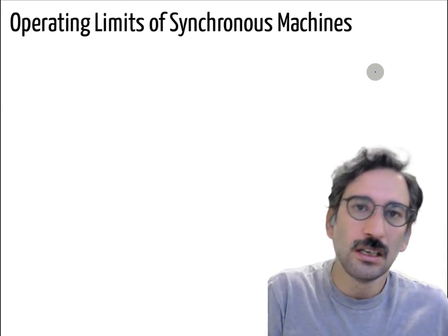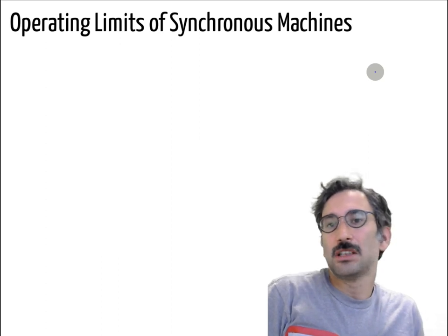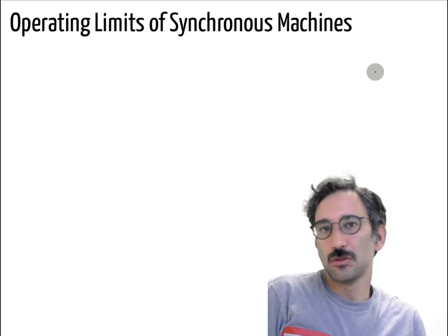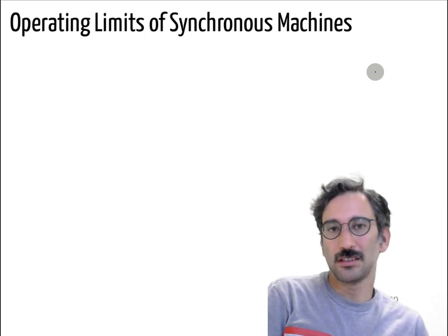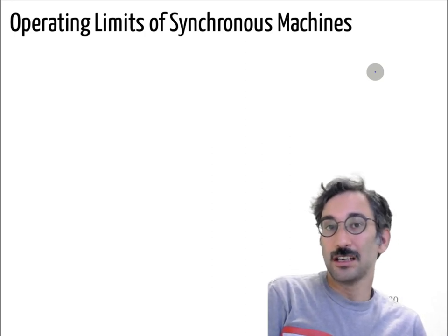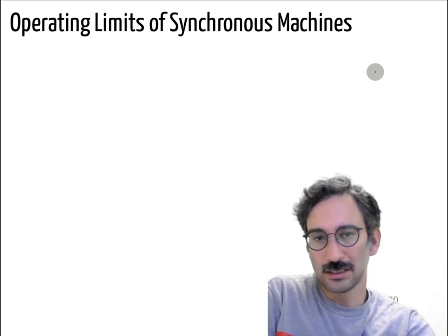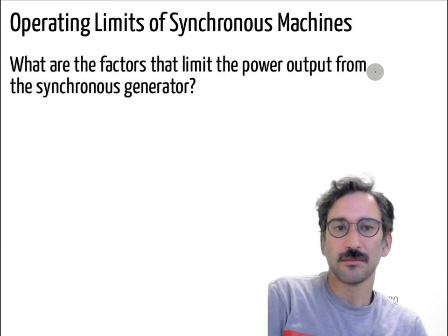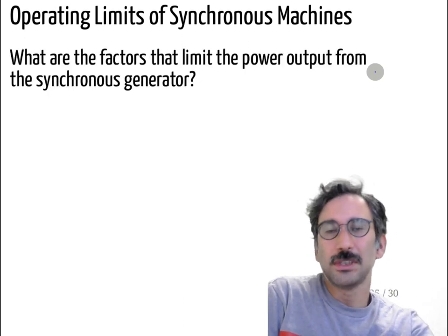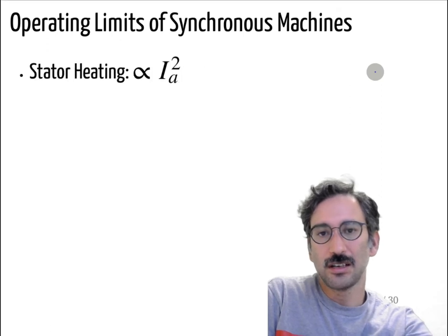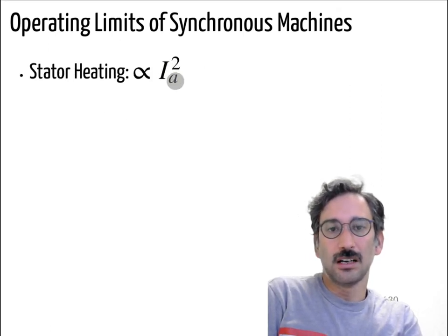Okay, so if you have some kind of synchronous machine, what are the operating limits? For example, if it is written 100 kilowatts on the motor, can I run it at 200 kilowatts, or why not? Let's have a look at those operating limits. First of all, one limiting factor of a synchronous generator can be the stator heating. It is proportional to armature current.